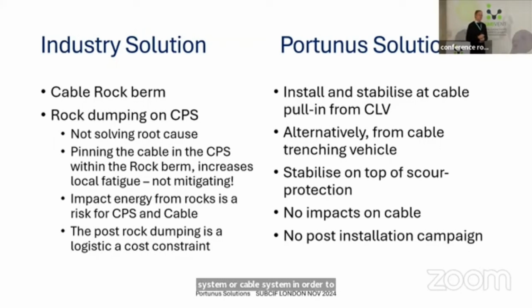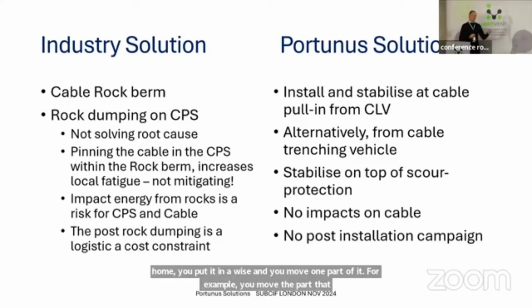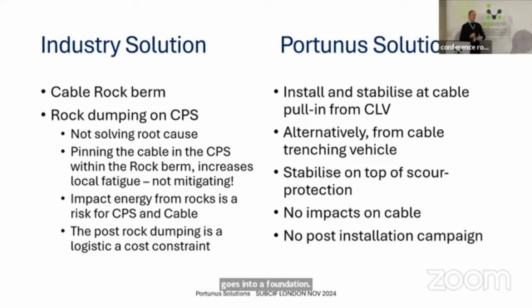It's like you take a cable you have back home, you put it in a vise, and you move one part of it. For example, you move the part that goes into a foundation. You move that in the water column and you have one part of it pinned under the scour protection. You basically should not be very surprised if one day it breaks where it is pinned into the scour protection.